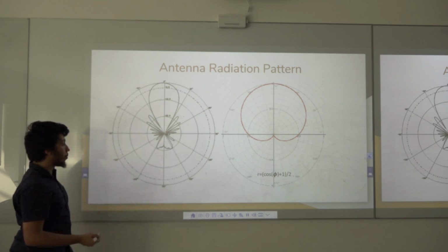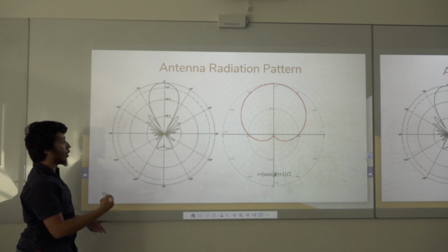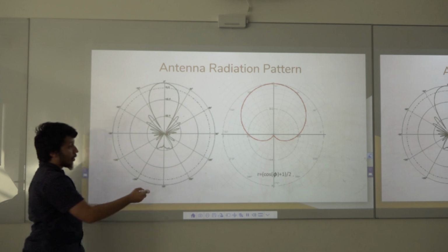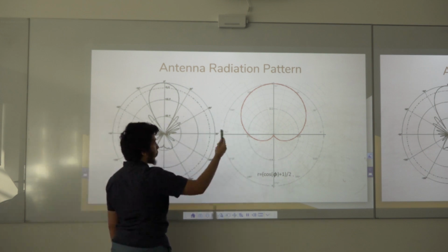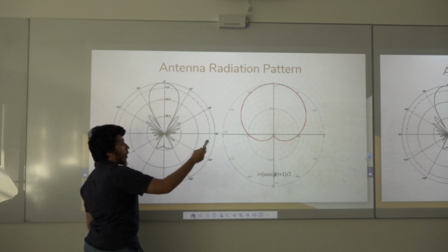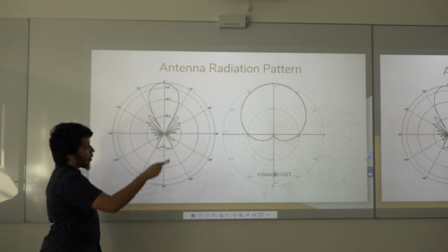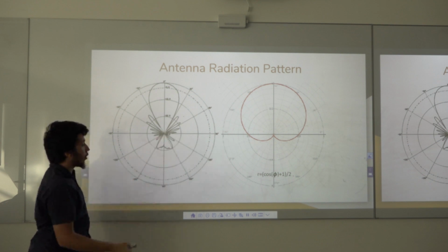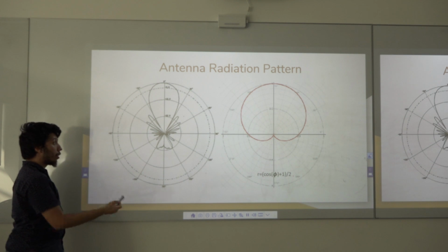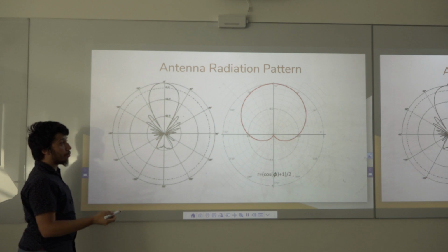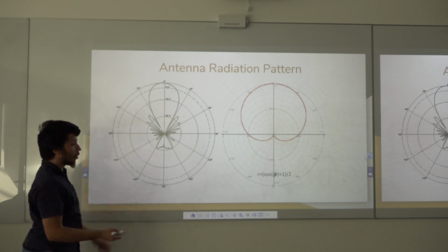which should normally mess up the reference, but since our system will use discrete values, just indicated by whether the signal strength is less than or greater than the reference signal, what we use for a model is a much simpler function which takes that same pattern and has one point where the signal strength is 1 at 0 degrees, and then all around the circle has a signal strength that's less than 1. This is the model that we use for a Yagi antenna, and the signal strength that we extrapolate in our system model is based on this function.